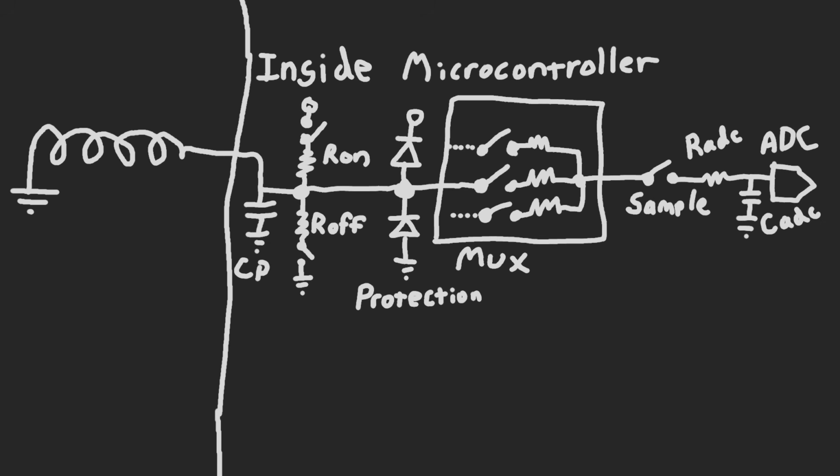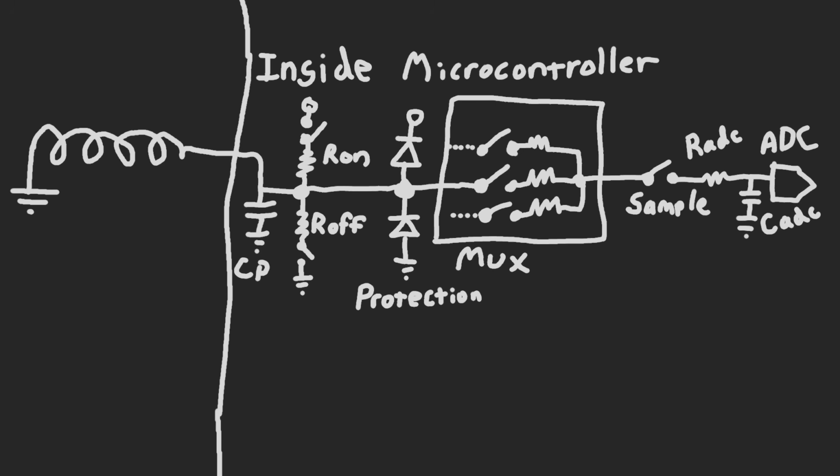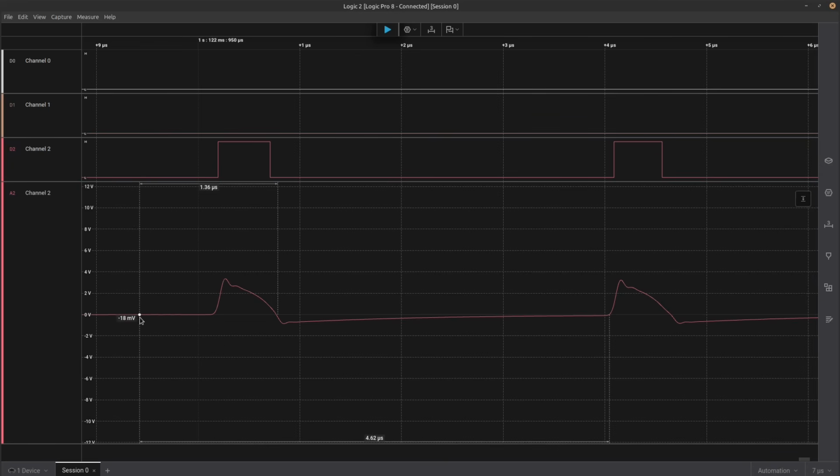What I mean by opens up the gate is there's a mux internal to the ADC. That mux will open for a short time for the ADC capacitor to be charged and be able to actually start sampling and measuring the signal. So we're able to start at different times back here so that the gate will close at various points here, and we can measure the exact voltage at different points along this arc.